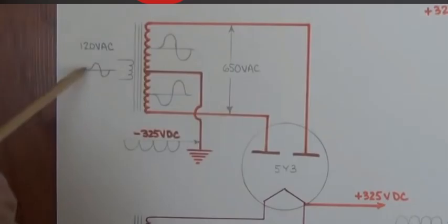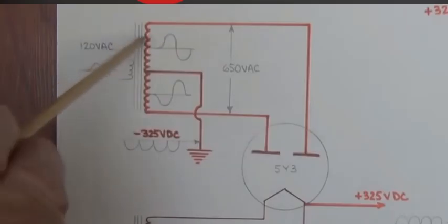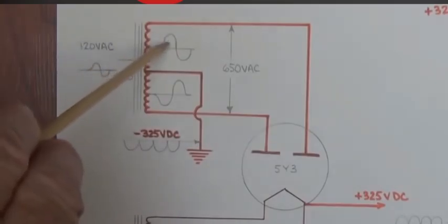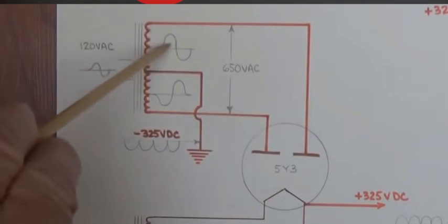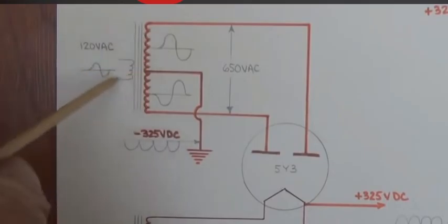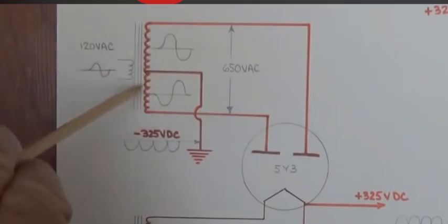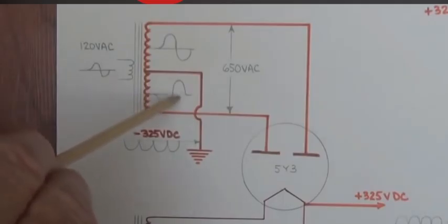And it does one other thing, which will remind some of you of an output transformer, but backwards. It takes the 120 cycle signal, and it not only makes it 3 times bigger. Remember, we turned 120 into 325. It's almost triple. But it also, the upper winding here, leaves the pattern of the alternating current alone. Up is up, down is down. The lower part here, the lower winding, or half winding of the secondary, has the mirror image.